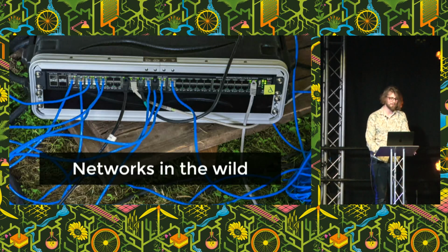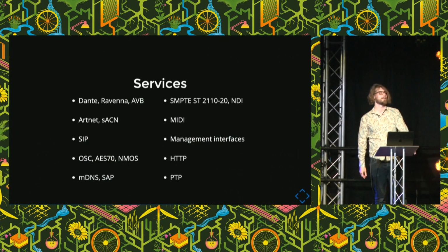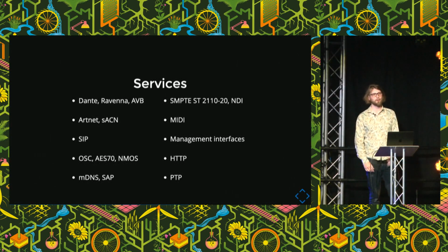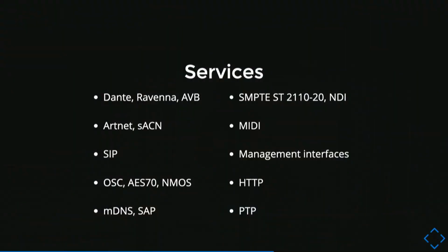So now that I've made that point, what are they actually running on the network? A lot of stuff that you may or may not have heard of if you've done any Pro AV before. There's like 3, 4, probably 5 different network audio standards. The one in use here is Dante. A lot of vendors are going for AVB. Ravenna is also a thing, but mostly in broadcast.